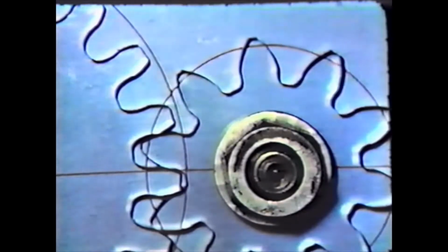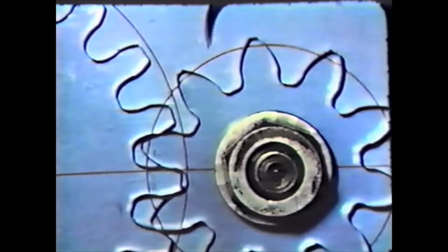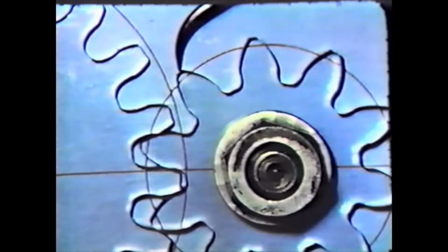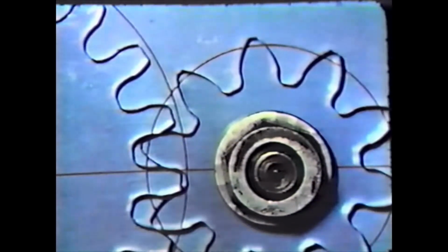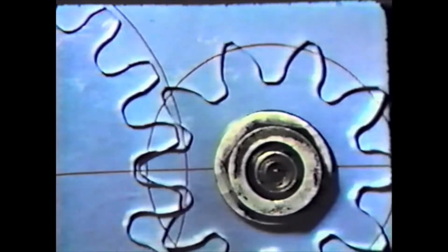If the same center distance and tooth ratio must be maintained, another method is to enlarge the pinion diameter and reduce the gear diameter a proportional amount. This slightly reduces the length of involute profile on the gear tooth and increases the strength of the pinion tooth.